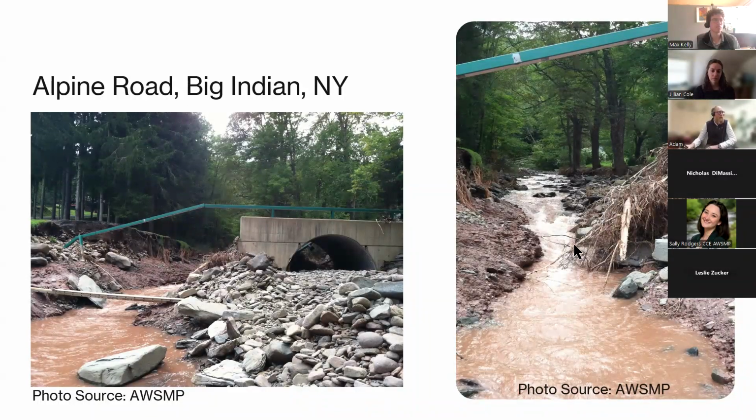A lot of the sites in the Catskills get complicated by the geology of the Catskills. So you can see in this picture, this right bank here, looking upstream, the presence of some lacustrine deposits that were linked to the last ice age. So when that material, which is typically overridden by alluvial sediment, so the boulders and the cobble, it oftentimes leads to a very quick unraveling of the stream channel and incision process that leads to that drop in bed elevation.